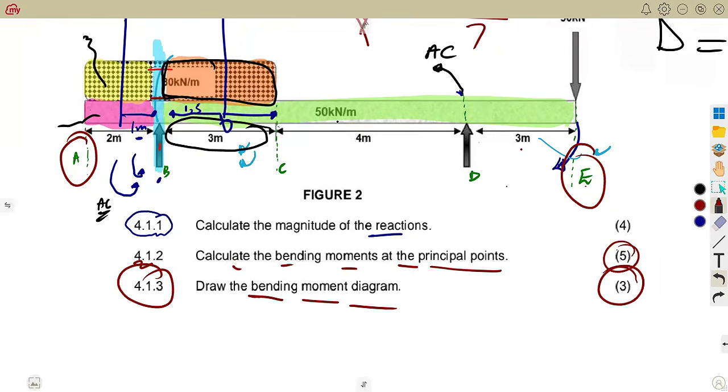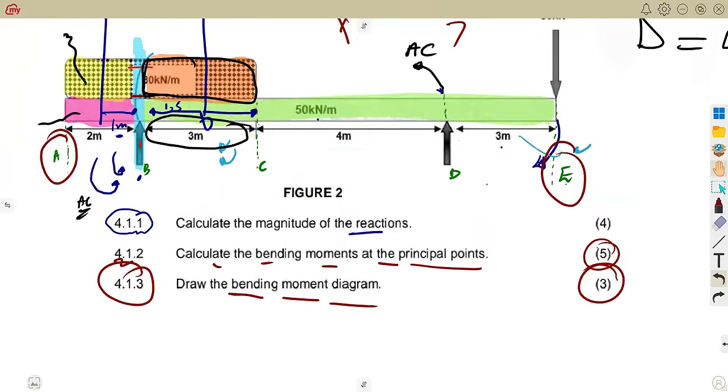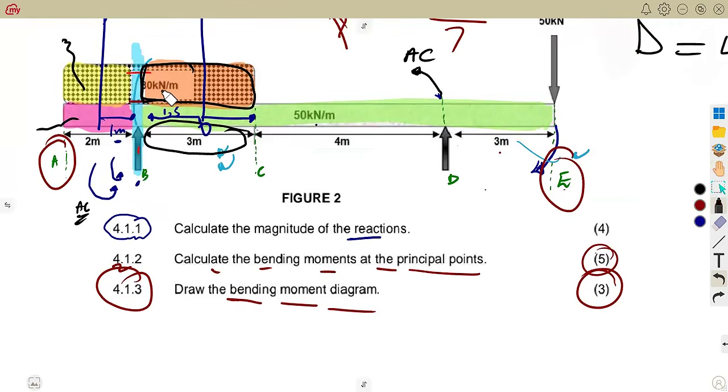So if you are to consider, I said when you are to have your bending moment diagram, here we've got a distributed load. It's distributed throughout, guys. So meaning to say, we are going to be representing it in form of a curve. It'll be in form of a curve when it is distributed, when you're representing the bending moment. Also, on the bending moment diagram, we calculated those bending moments, but we need where it is going to be maximum. Where do we have the maximum bending moment?